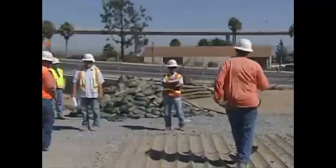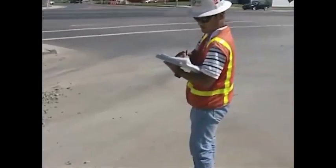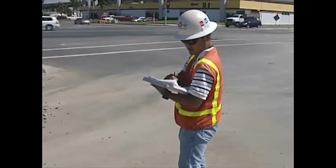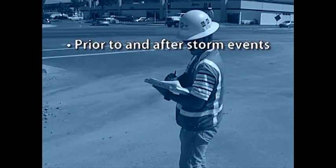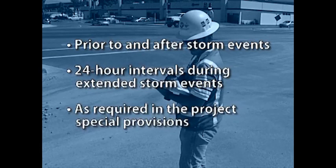Inspections are also required during dry weather to ensure proper implementation of BMPs, such as those for sediment tracking control that are not necessarily weather-related. During the rainy season, inspections must be completed by the contractor prior to and after storm events at 24-hour intervals during extended storm events or as required in the project special provisions.